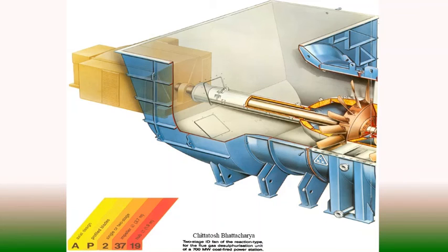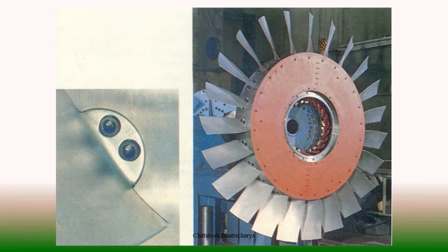There are stiffeners to withstand the casing, because there is a change in direction in the axial flow fans. Suction is axial and discharge is also axial. So naturally there are some directional vents also, and a horizontal splitting arrangement is there to prevent eddy formation in the flow passage.